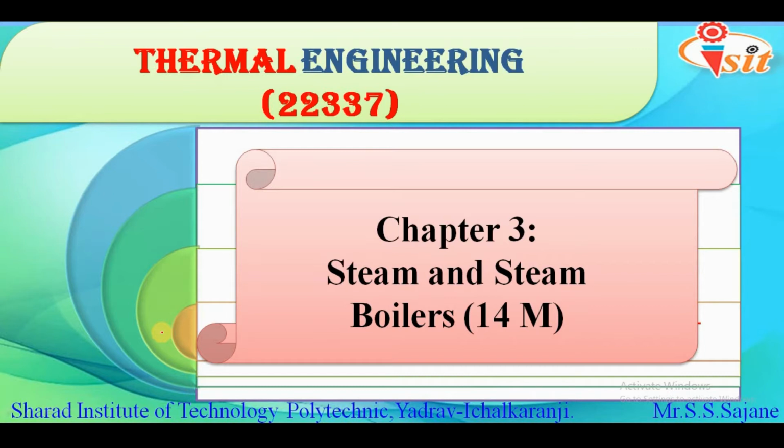Before that we have also studied the meaning of sensible heat and latent heat. Then after studying the formation of steam from ice, we have studied several properties of steam such as enthalpy, entropy. Then again we have seen the various conditions of steam, like the meaning of wet steam or dry saturated steam and superheated steam, along with the concept of degree of superheat. Then we have also studied the temperature versus entropy diagram.